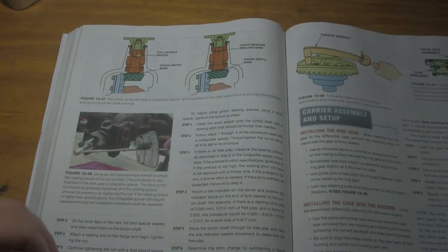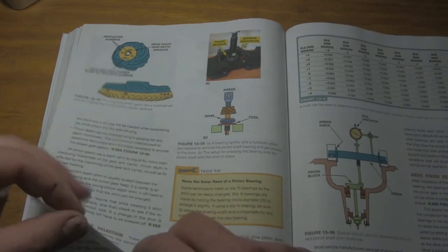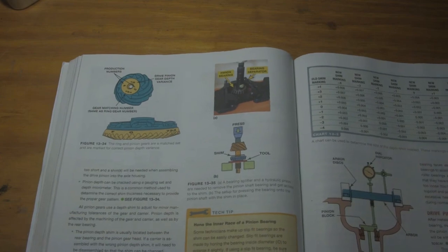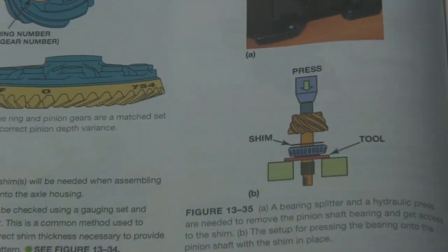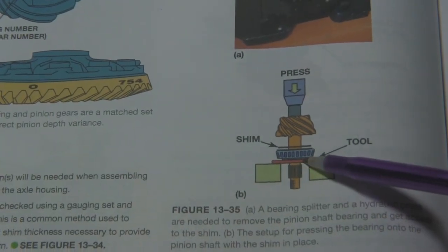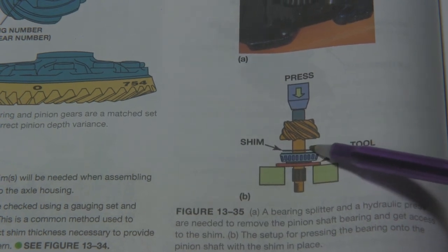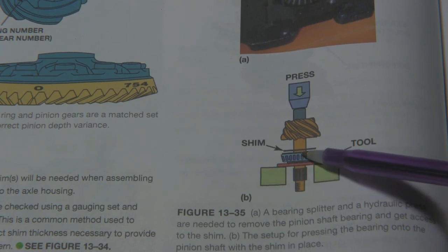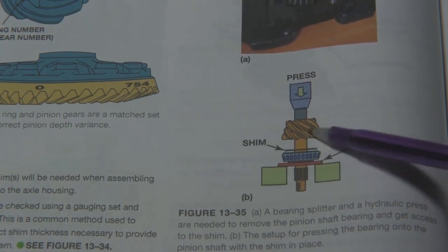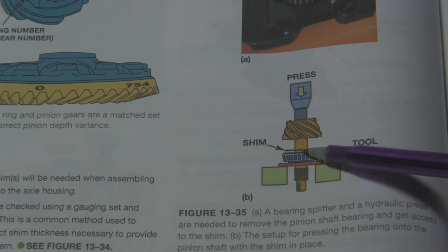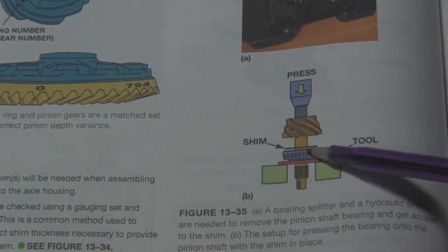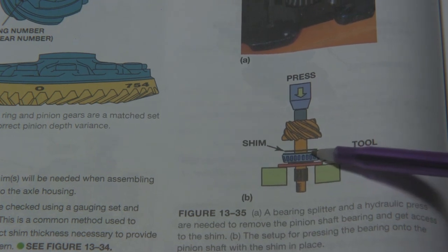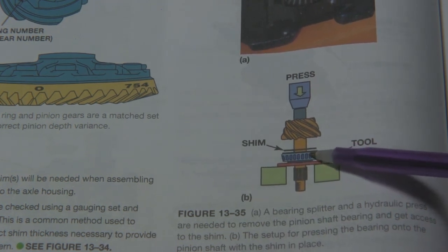Something else that rebuilders will do, people that do a lot of rebuilding, if we take a look right here, this is a pinion gear. This pinion gear has a shim right here, okay? So what I'm talking about, this bearing has to be pressed up to this pinion gear, but there's a shim in place. And so if my contact pattern is incorrect, I'm going to have to pull that bearing back off. And if I can't get behind the bearing in order to catch the center portion of the bearing, I'm going to end up breaking that bearing.